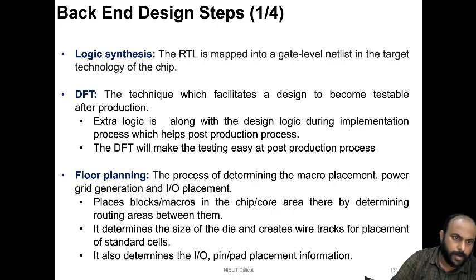During logic synthesis, you can also do something called DFT insertion. As I already told, DFT stands for design for testability. In this stage, techniques are applied which facilitate a design to become more testable after production.